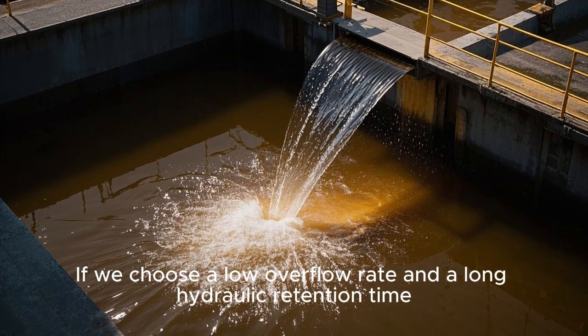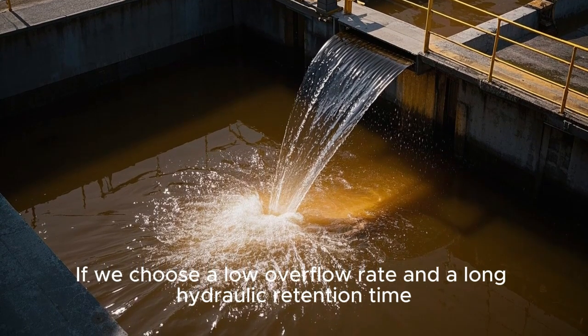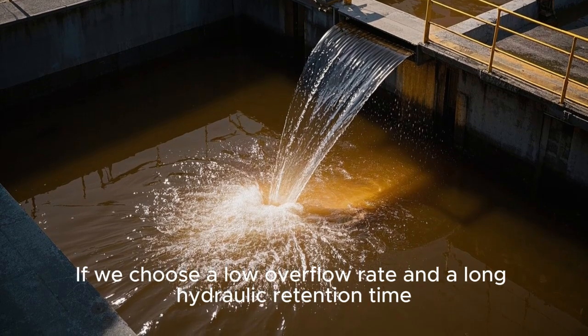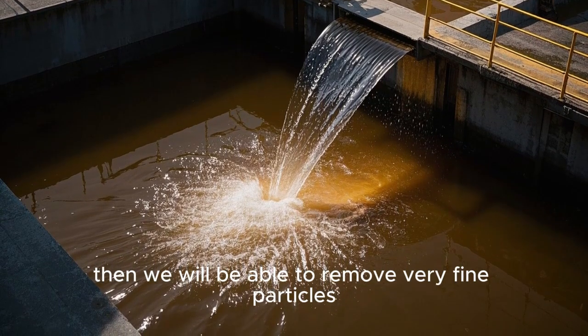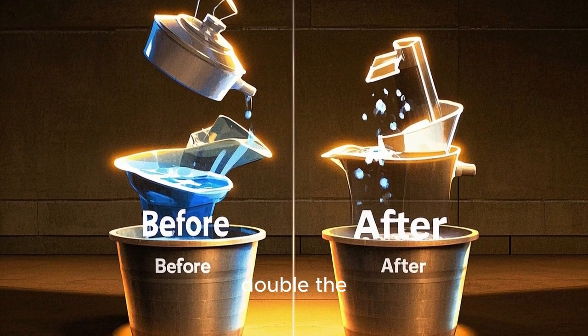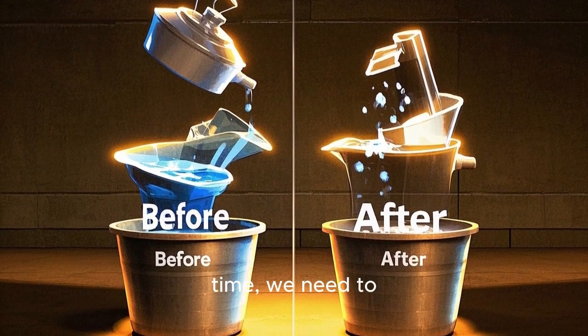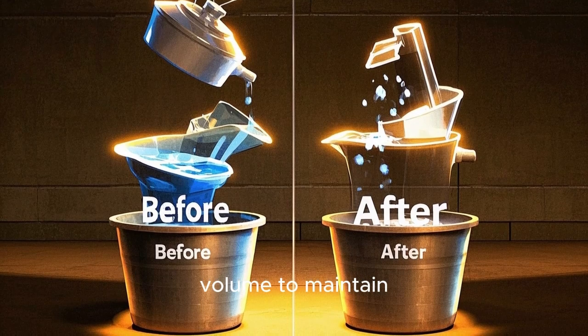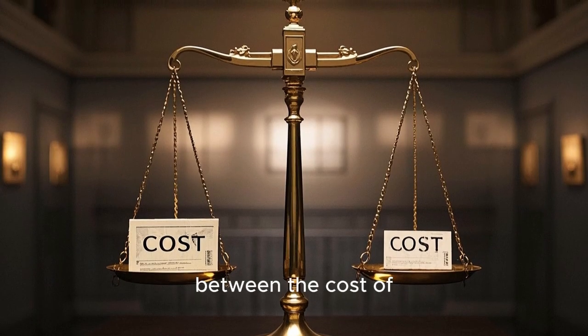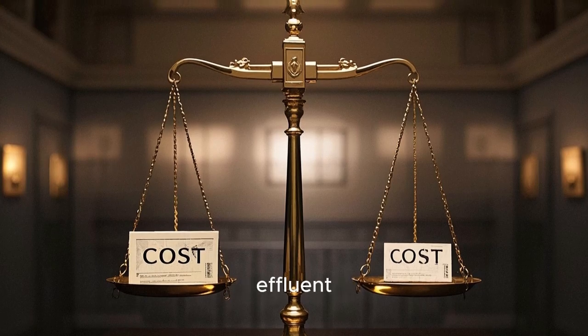If we choose a low overflow rate and a long hydraulic retention time, then we will be able to remove very fine particles, but this comes at a cost because we need a very large basin. For example, if we double the hydraulic retention time, we need to double the basin volume to maintain the same overflow rate. There is a trade-off between the cost of the basin and the quality of the effluent.